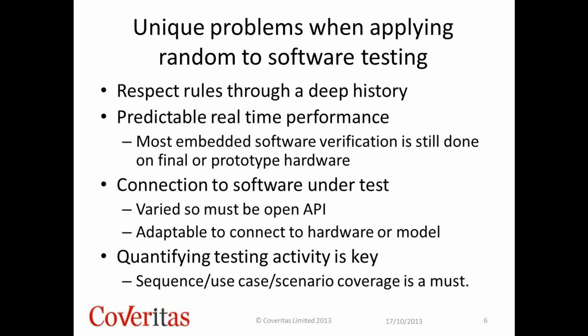First of all, real-time performance. Now, in the tools that existed before, they were working in a simulation environment. Performance wasn't a big deal. Most software verification today, or certainly my experience, is done with the real system. It's done with FPGAs or with real silicon, with real software compiled onto it, and that's where we do a lot of our verification. So this system that I'm talking about has got to be able to constrain or control randomly generate data and pass it into that system in real time and be able to monitor data in real time and work with that.